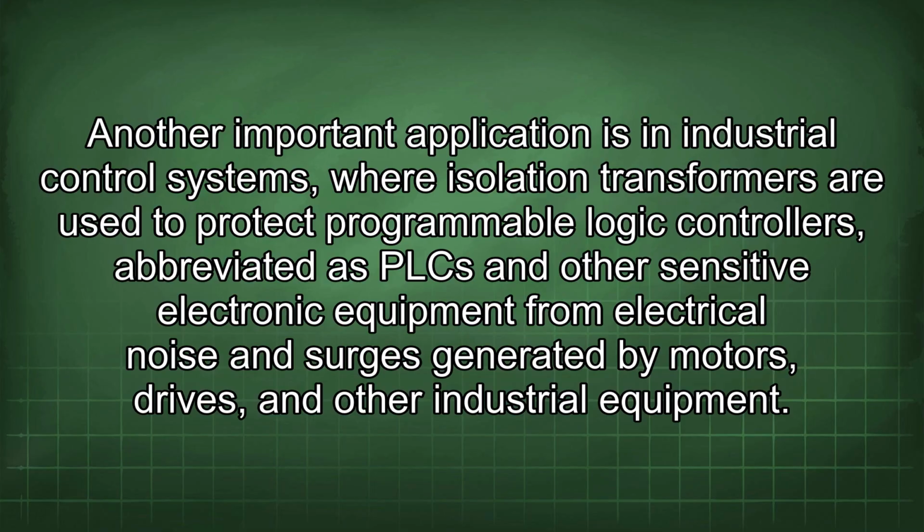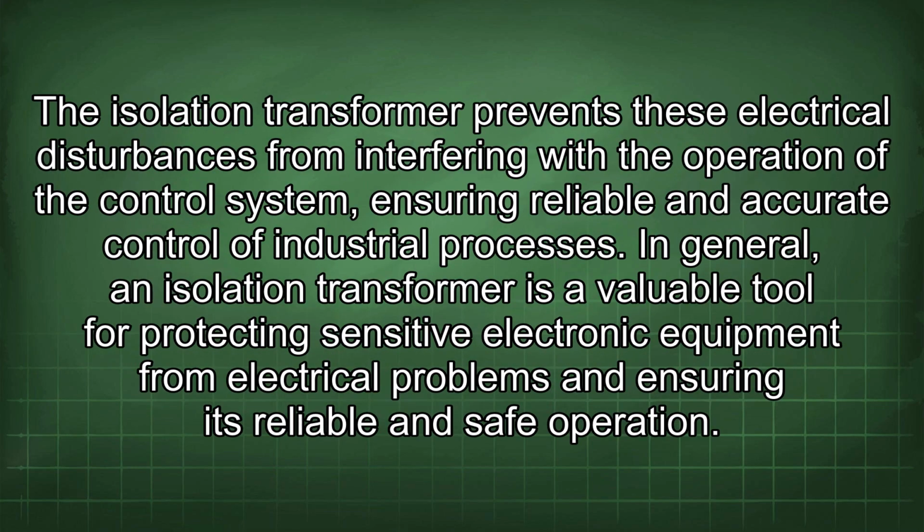Another important application is in industrial control systems, where isolation transformers are used to protect programmable logic controllers, abbreviated as PLC, and other sensitive electronic equipment from electrical noise and surges generated by motors, drives, and other industrial equipment. The isolation transformer prevents these electrical disturbances from interfering with the operation of the control system, ensuring reliable and accurate control of industrial processes. In general, an isolation transformer is a valuable tool for protecting sensitive electronic equipment from electrical problems and ensuring its reliable and safe operation.